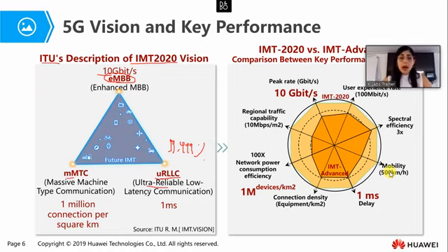And when we talk about low latency, we are talking about a latency as low as 1 millisecond end to end. So here we can make a note. When we talk about 1 millisecond of latency end-to-end, first of all, we are talking about the user plane latency, not the latency related to the control plane. So 1 millisecond is for the user plane.